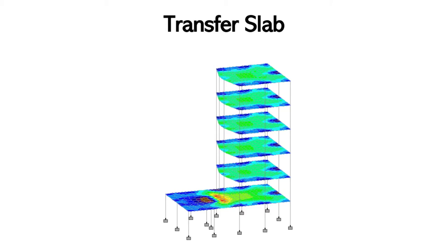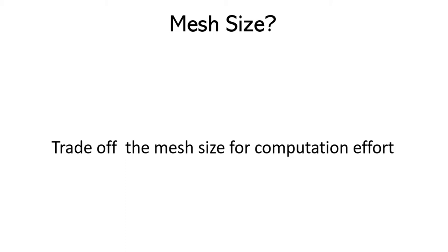Now, another important point which most of our users ask, and the answer to that question would decide the selection of the rigid or the semi-rigid diaphragm. For the rigid diaphragm, even if you're meshing it, for example, in RAM Structural System, all those internal nodes of the meshing would be taken as a consolidated one for the in-plane action of that floor, and the degrees of freedom for each floor would be taken as 3. That means two in-plane lateral actions, and one rotational degree of freedom.